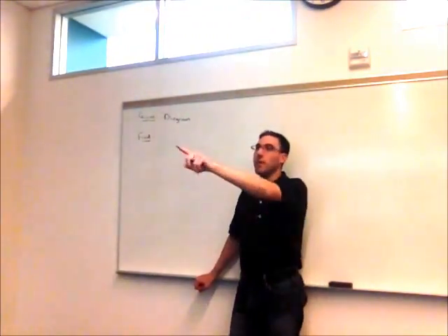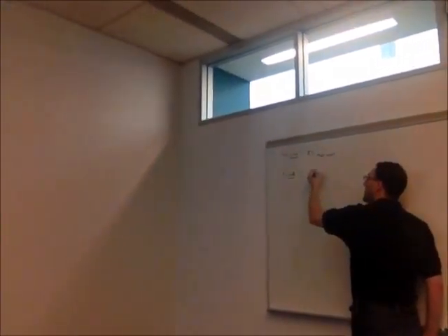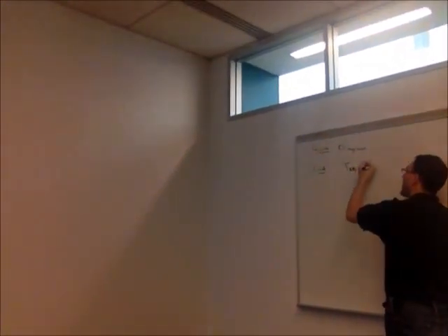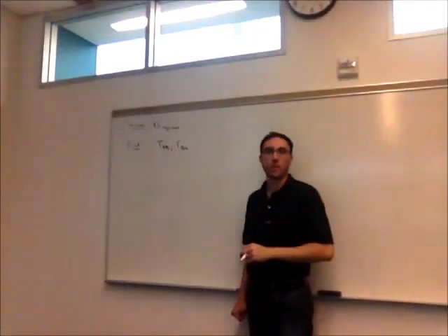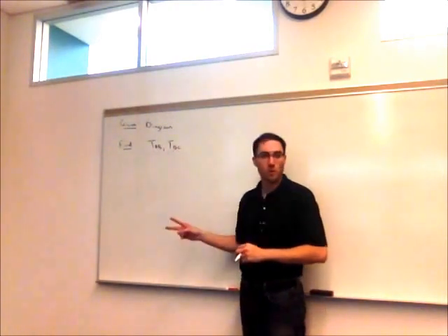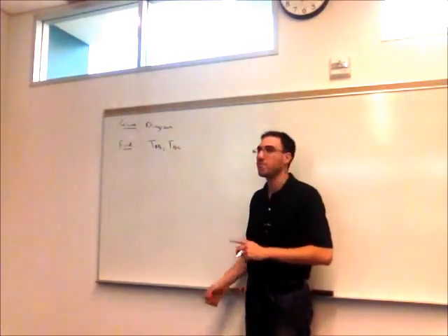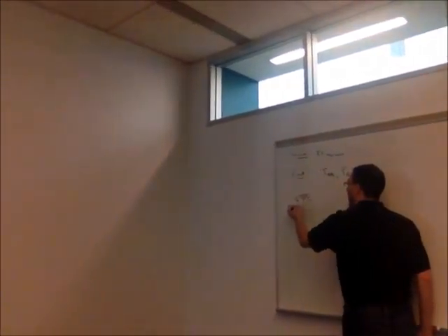Right, so there are the tensions in those two cables. I'm going to call them TAB, TBC. You could name them whatever you want. Here, it was given to us so we know what we're looking for. So two things we want to know. They're both forces, and we know they're both in tension. So now a crucial step, maybe the most important step of this process, the free body diagram.